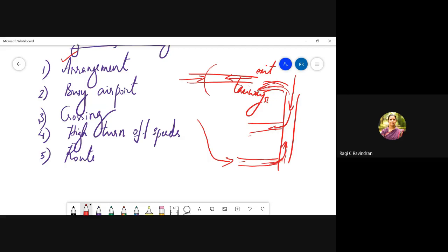Okay. So in the case of busy airports, whenever the aircraft is landing, okay, maybe at this point it will come to a halt. Okay, the landing distance is 60% of the total distance, right? So at this point it will come to a halt, and then it can slowly go ahead and exit the runway through this exit taxiway, and it will be able to reach the apron.